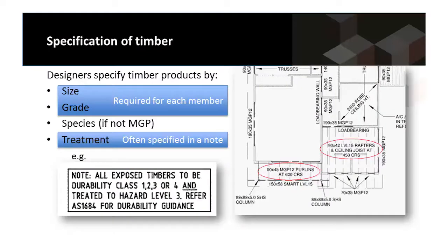And just check that the classification looks okay. If you've got a building with a really great view over the ocean and the plan says N1, it's probably wrong. Okay? So that wind classification is important.